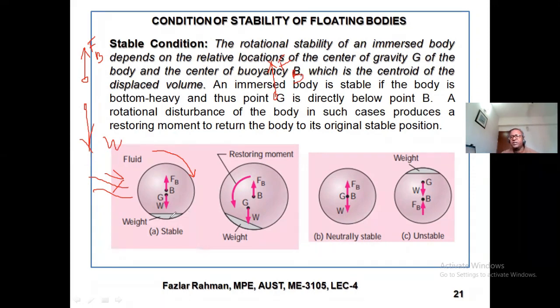For example, you are in a boat, the boat is floating straight. So how much volume is displaced, how much volume is underwater, differs by the area, right? But say due to the wave, it inclines. Now the water displaced by the body is not the same as the previous one. So that's why you see the buoyant force magnitude will change, and also the center of gravity will shift due to the rotation.